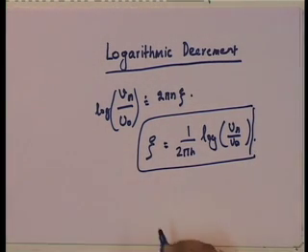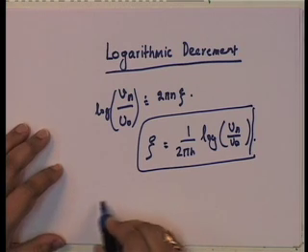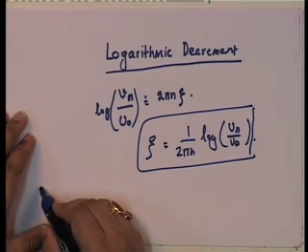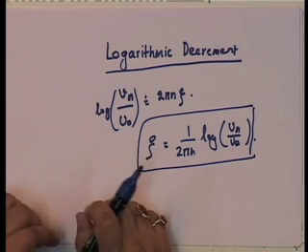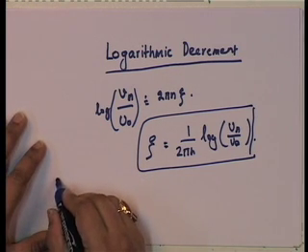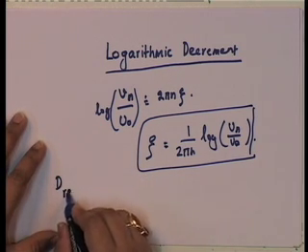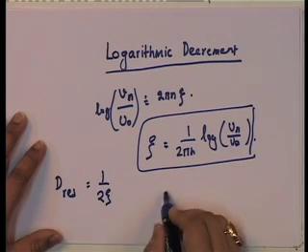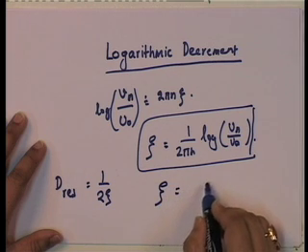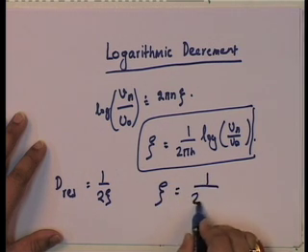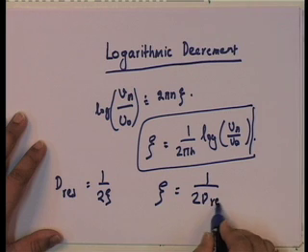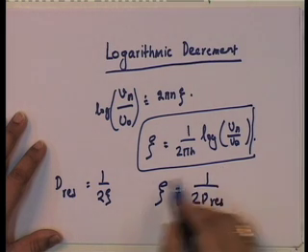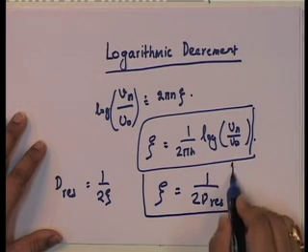We also saw another way, didn't we? We saw that if you plotted the dynamic amplification, what was D at resonance? D at resonance was 1 upon 2 xi. So xi could be obtained technically as 1 upon 2 D at resonance.